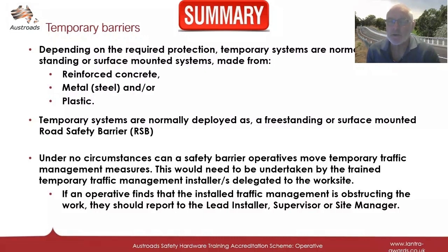And under no circumstances can a safety barrier operative move temporary traffic management measures. This would need to be undertaken by trained temporary traffic management installers delegated to that worksite. If an operative finds that the installed traffic management is obstructing the work, they should report to the lead installer, supervisor, or site manager.